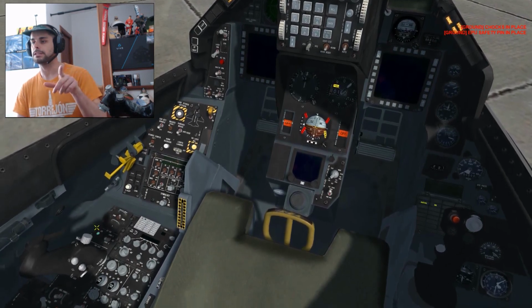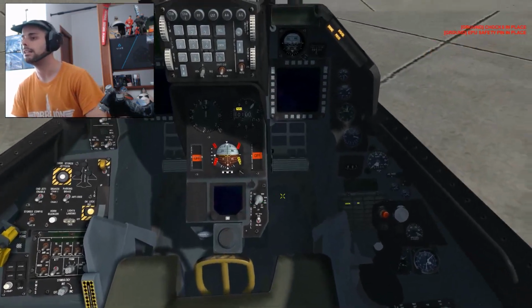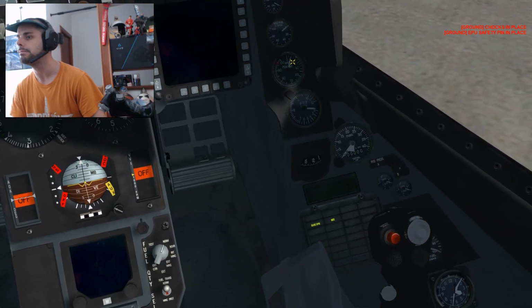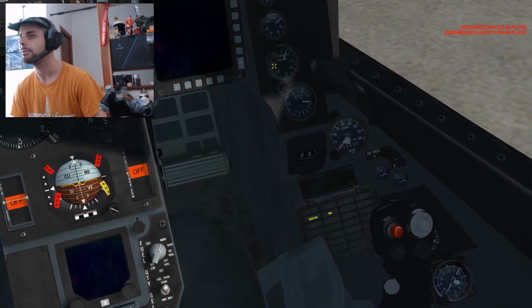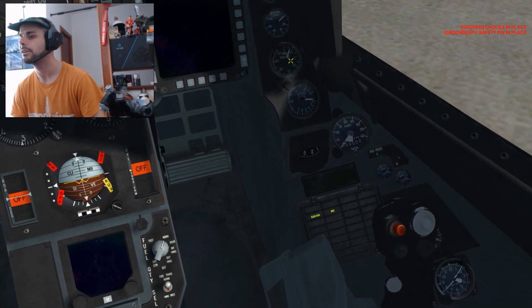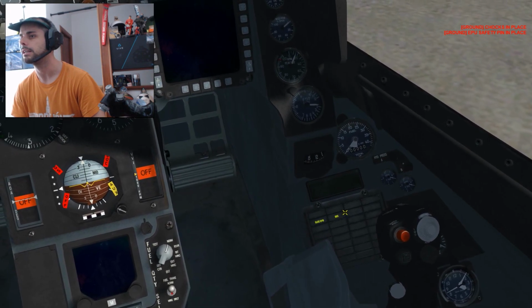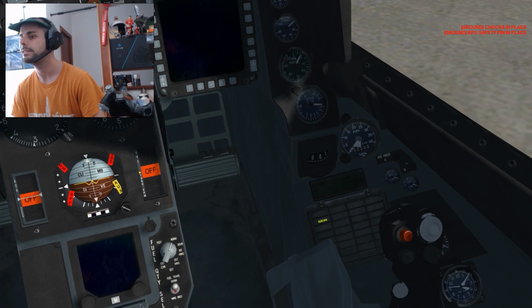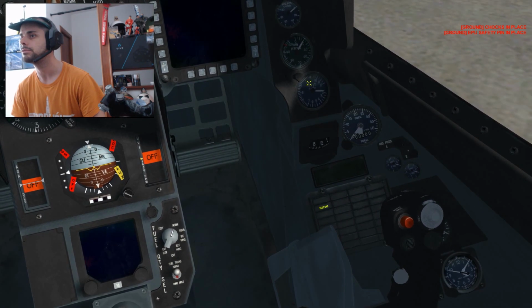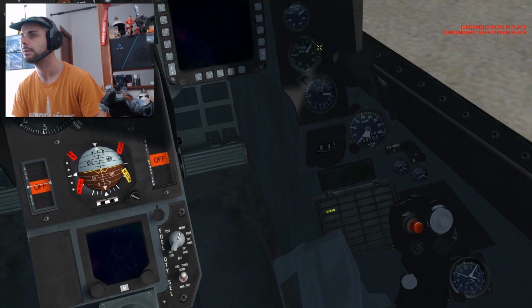Light on the left, as you can see now, and also the RPMs are now increasing. Look at the check light. For the moment, do nothing. Only look at RPM and check light. Now that the check light is out, you can wait until 20% or maybe 25%.